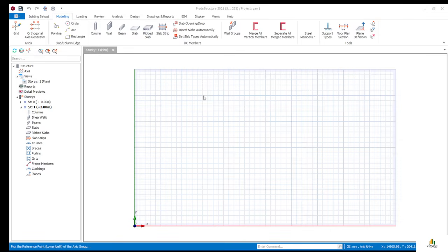So at the dialog box, as a grid generator dialog box, it says, as a spacing, you can delimit values with a comma character if unequal spacings are used. Repeating spacings may be entered using asterisk as a multiplier, provided that the spacing is written before the number of spans. Do you get it? In my example, you have 5,000, 2,000 asterisk 3.